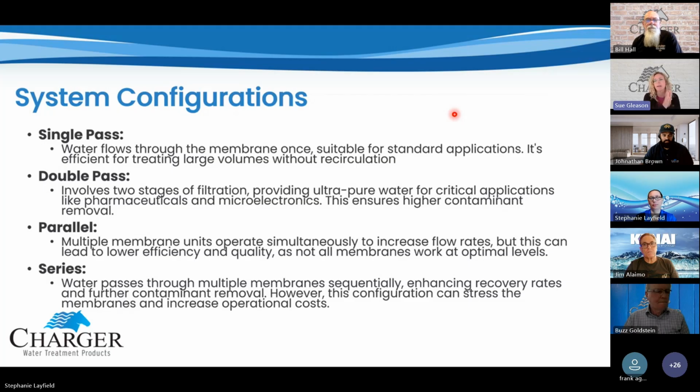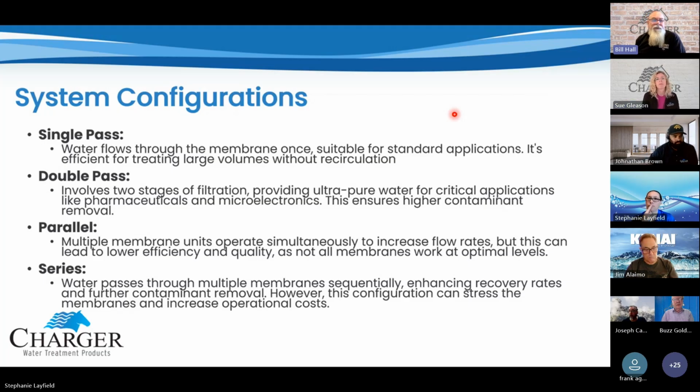In homes with greater than 30 hardness, with four in the home, for POE RO, would changing the membrane annually be an option instead of a softener? Yeah, there's a lot of times that people, whether it's a home RO or a commercial RO, I've seen people for whom it's easier or cheaper to replace membranes than it is to put in pre-treatment. Again, it's a judgment call on their side on what they want to do.